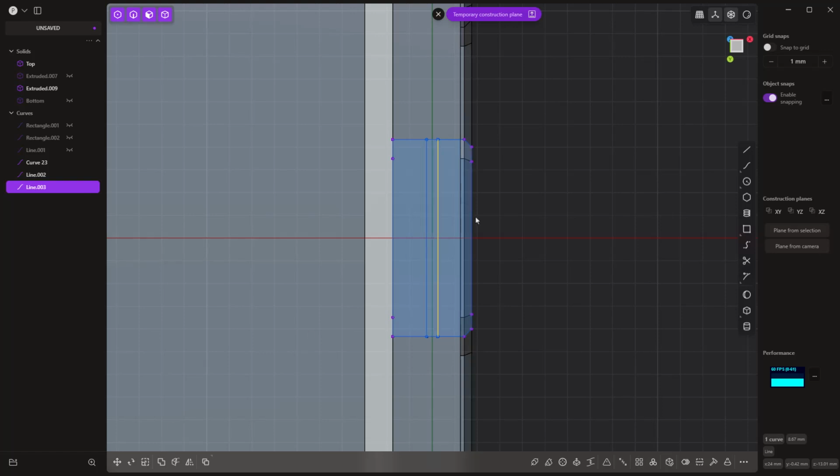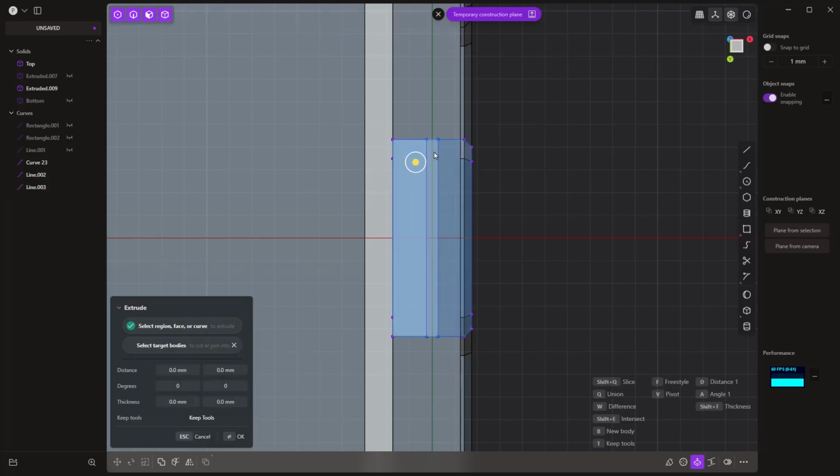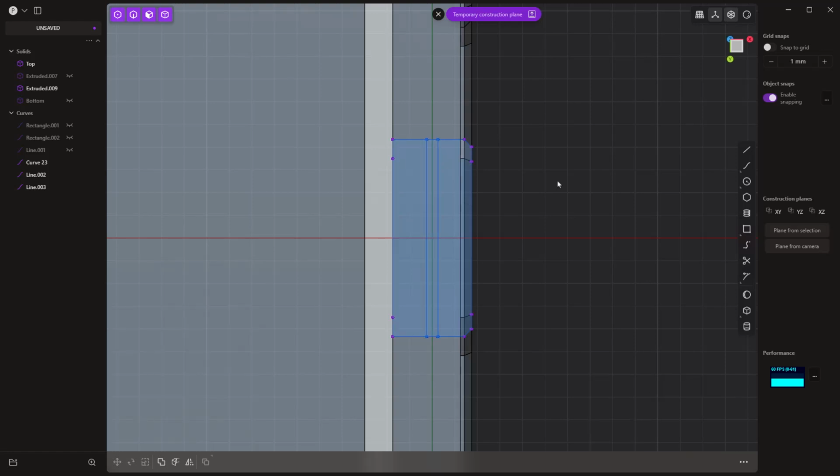This button only needs to flex inward, so toward the center of the box, and this will give us two profiles that we can select. One that'll allow us to extrude or cut away material, and one that'll allow us to add material back. One thing that we should also consider is the sides of this are perfectly matched, the exact same size right now, and we do need a little bit more of a gap over there.